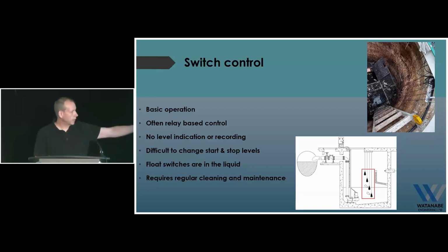So as you can see on the diagram at the bottom there, at least one of the float switches, the low-level switch, is always going to be in that liquid. Usually the start level switch is also going to be the stop level switch, is also going to be in that liquid 100% of the time. And then the other two, the start level and the high level float switch, will be up out of the liquid, so only seeing it a few times.